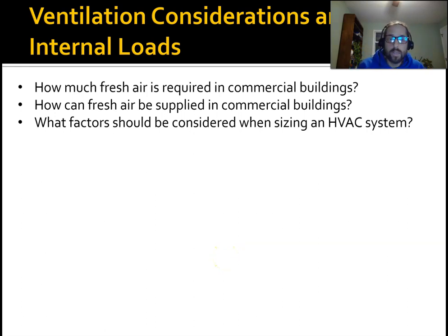Alright, so in this discussion I'm going to go over ventilation considerations and internal loads. So we'll go over the fresh air requirements for commercial buildings. There's actually code that specifies certain amounts of fresh air per person. And we'll go over that and go over that calculation. And then go over a few ways that you can supply fresh air in a building.